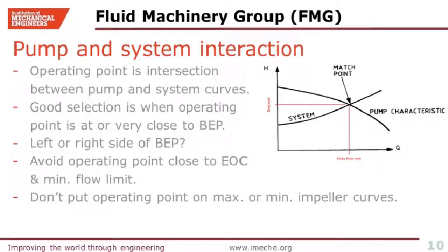It is fair to say that manufacturers normally design each centrifugal pump with a given impeller and given operating speed for only one single operating point, and that's BEP, because there is only one BEP on each curve.